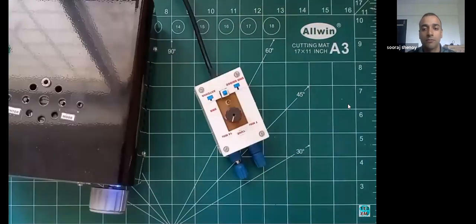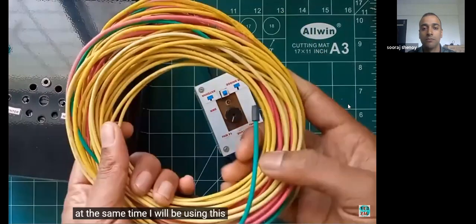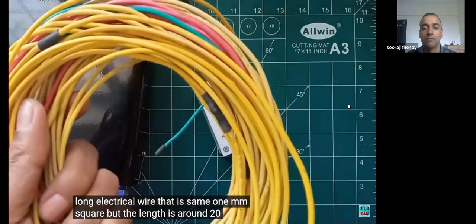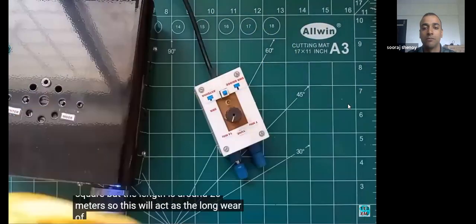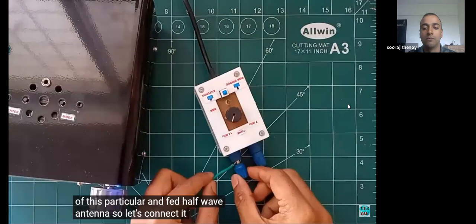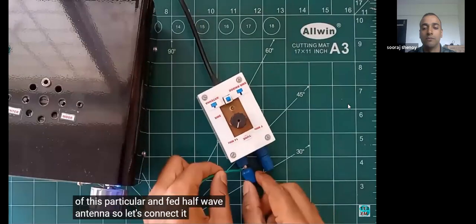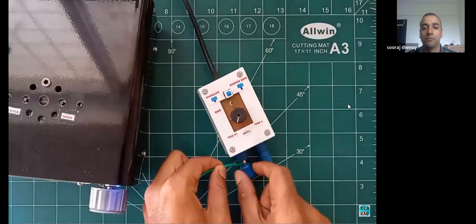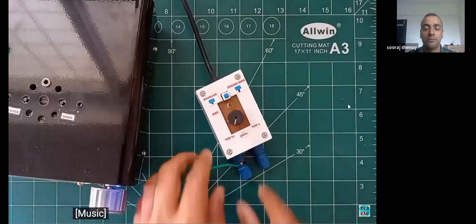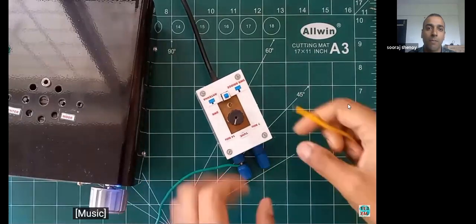At the same time, I will be using this long electrical wire, the same 1 mm square, but the length is around 20 meters. So this will act as the long wire of this particular end-fed half wave antenna. So let's connect it. Connecting the counterpoise wire.